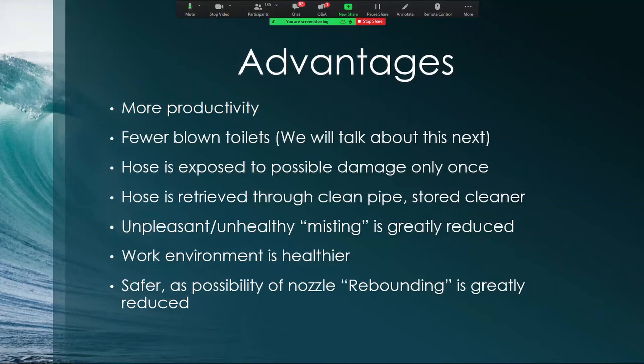But if the nozzle travels out at a high rate of speed and hits an object, be it a rock, a wall or something, and then deflects and goes up a service, now you've got trouble. If the nozzle hits the end of the pipe, bounces and comes right back inside the pipe, and now it's coming down all full steam ahead back towards the operator, now we have problems. If the nozzle is slowed down, instead of driving it down at a high rate of speed, but you walk it down the pipe, there's almost no chance for that nozzle to get deviated.